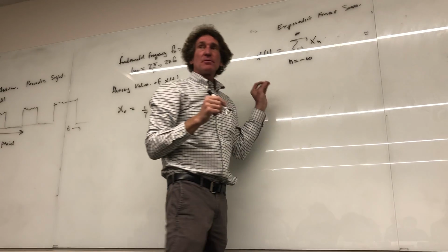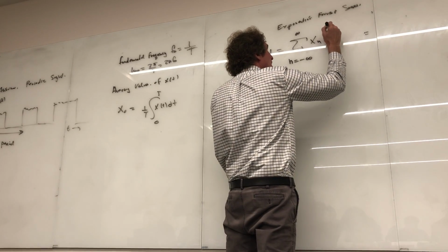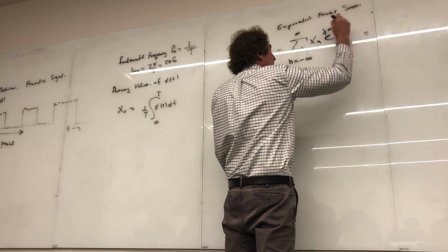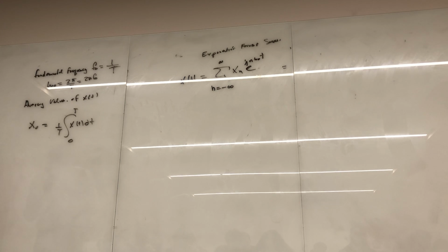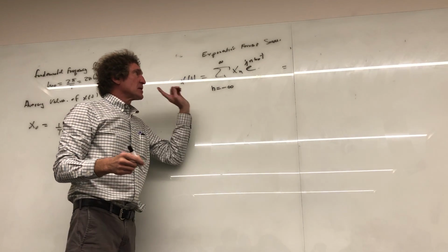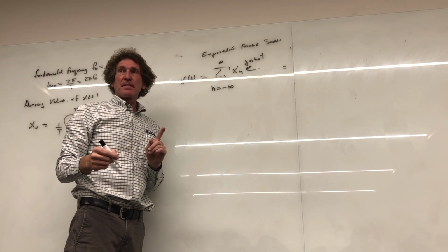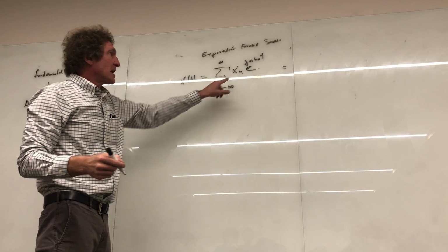That's a scalar value that we're going to calculate, times e to the j n omega naught t. Now, n's an integer, omega naught is 2 pi f naught, or 2 pi over T, and t is the time. We're going to take x of t and we create an infinite series, theoretically. Now, the question is, how do you get C of n?